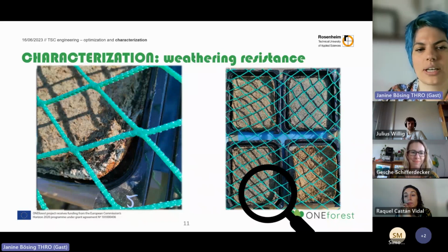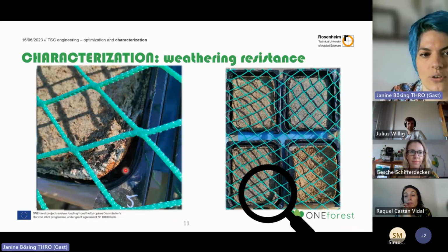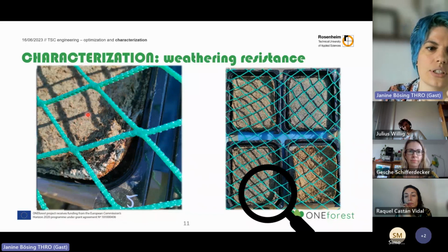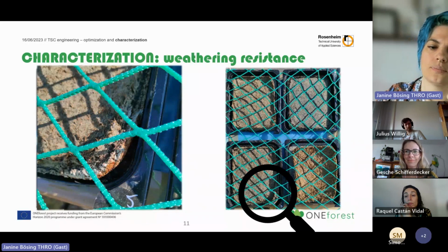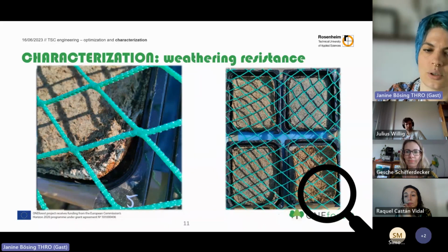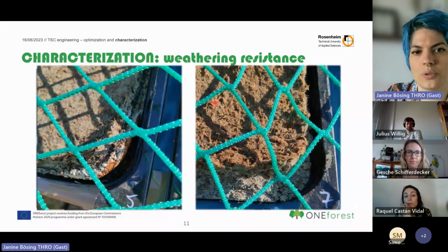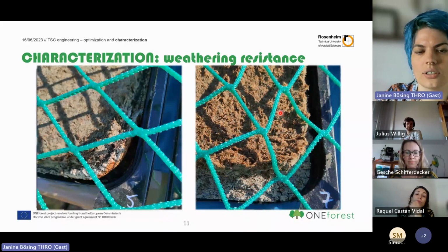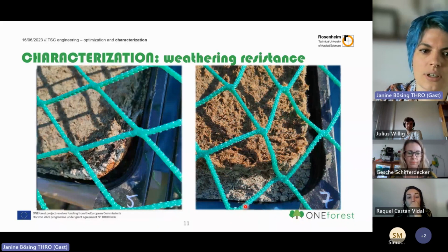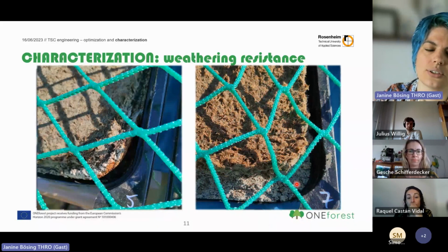And here in this topsoil cover, we can see that there's great adhesion between the topsoil cover and the soil underneath. So the topsoil cover was shrinking because of the great temperatures, and it lifted the whole soil with it out of the box. If you look at this other composition of topsoil cover, we can see that that's not the case here. We have also shrinkage and deformation of our topsoil cover, but it's not connected to the soil.